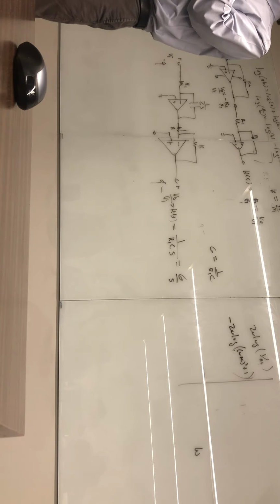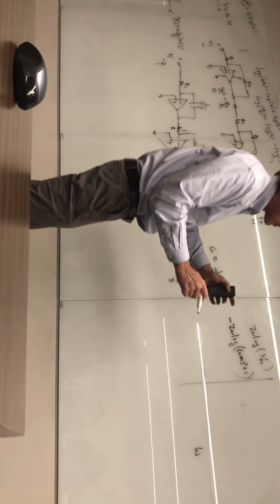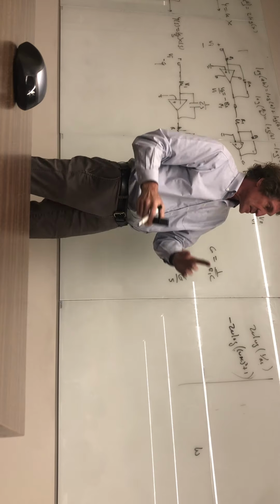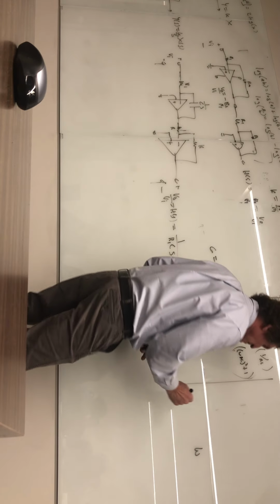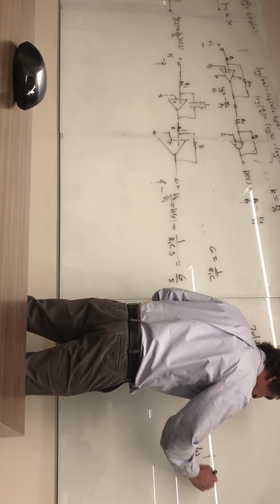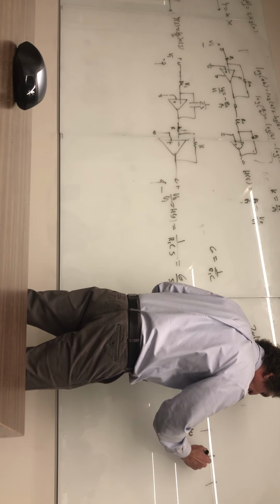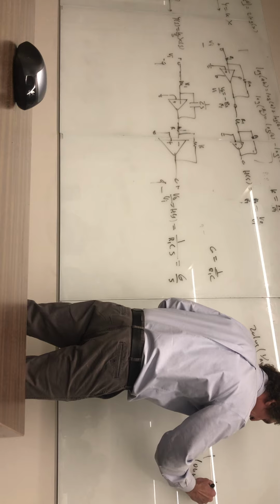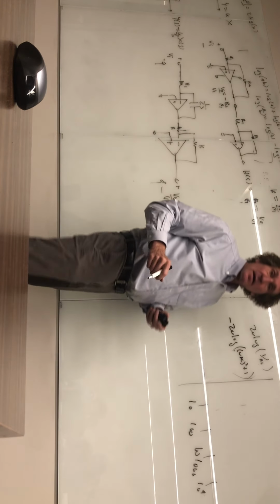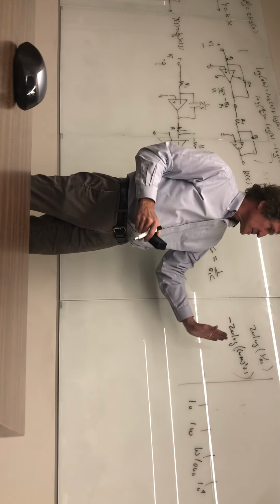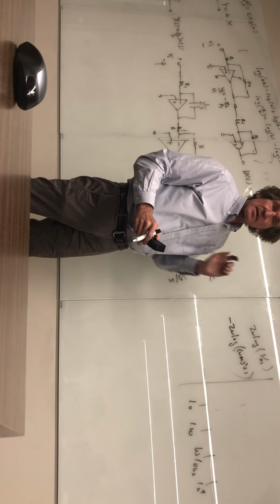I've just changed the form so I have 1 as the coefficient to omega RC squared. All right? Now, why did I do that? Here's why. When I plot this, it becomes easy for plotting purposes. Remember, that's magnitude, and by the way, this would be a logarithmic axis. The paper would take the log, so this would be 10, 100, 1,000, 10,000, and so forth, all right? So it's logarithmic on this axis. On this axis, you actually do take the log.